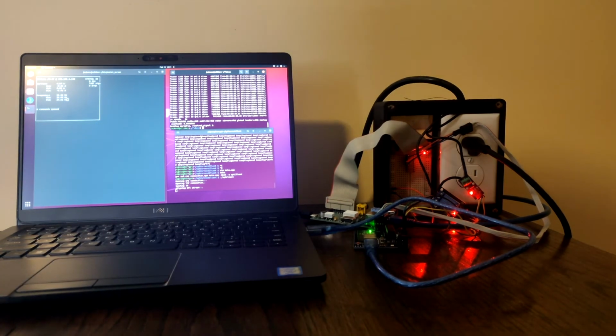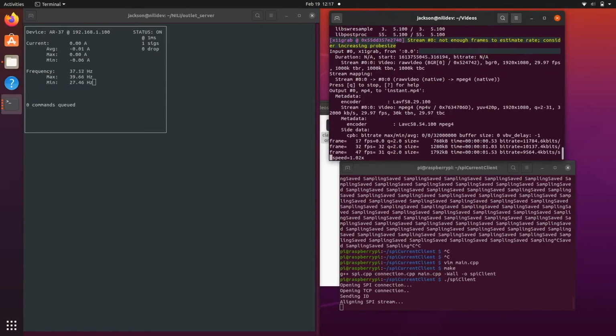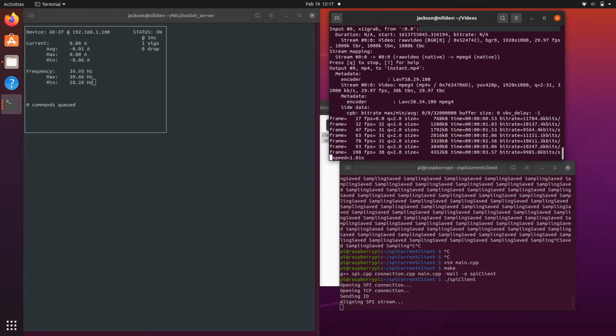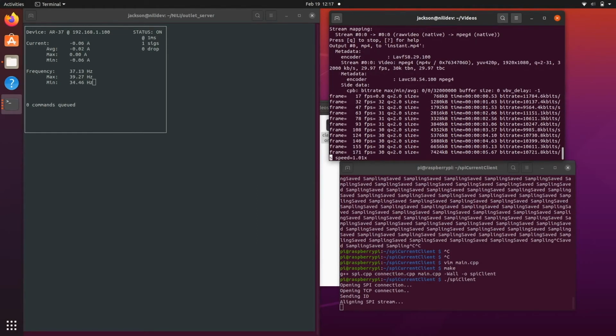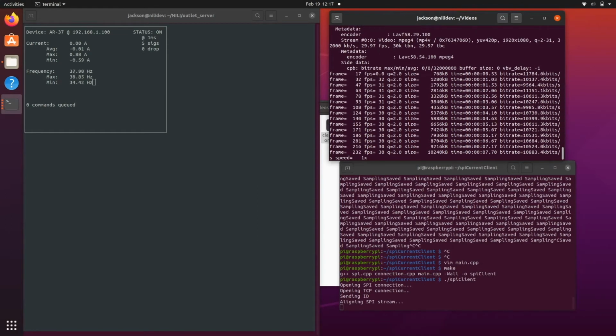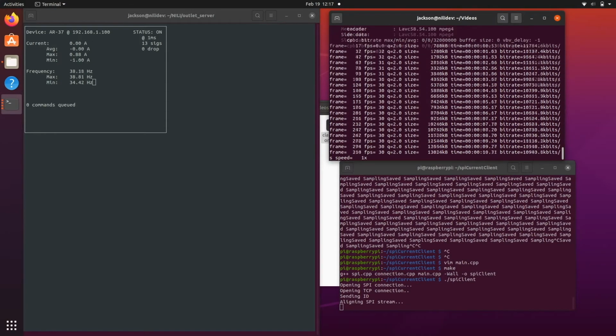The first program we wrote is the Instantaneous data server. We made it in Python and it listens for a TCP connection from the Raspberry Pi. It's over on the left-hand side of the screen. This server uses the raw values sent to our computer from our current sensor and maps the 0 to 5 volt analog value to a value between -30 and +30 amps. We use this for recording high-frequency data between 30 and 50 Hz.